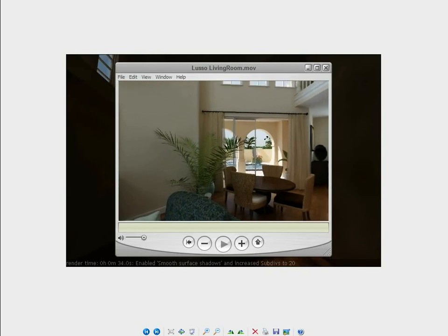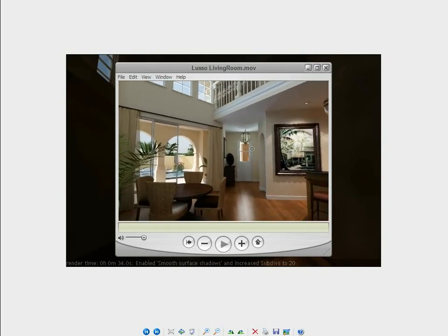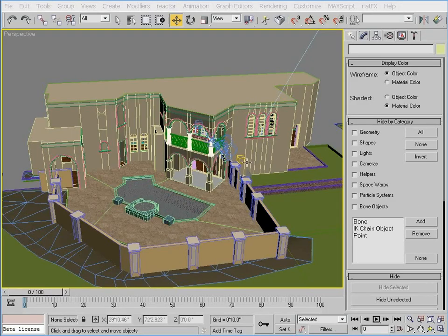Any windows off to the right-hand side, there aren't any, but if there were, those windows and door openings would have intensity values less than the window and door opening fill lights that I have here on the left-hand side of my screen. So from the outside, it looks like in this scene, I should start placing fill lights in these 3 windows here on the second floor.